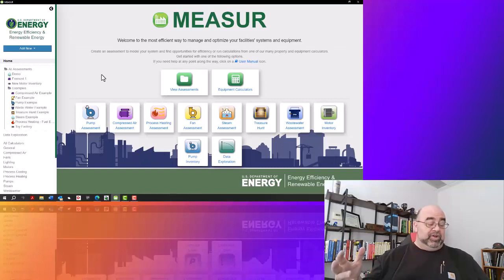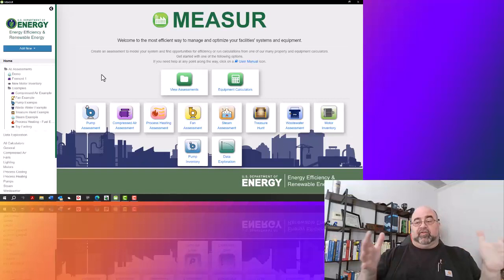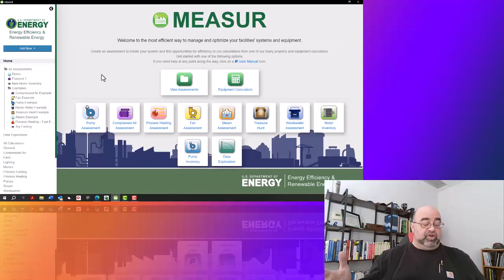So power measurement, you want to basically just record the usage, like several cycles or whatever the operational period is. You get several sets of that data and it gives you an idea of what the energy profile is for that equipment. Airflow measurements, when possible, and then pressure measurements, and those can actually be off of any pressure indicators in the system. And then, of course, leak detection. Now, leak detection is usually ultrasound. So you want to use leak detection systems. And both through the leak detection systems, but also by looking at pressure drop, you can make some improvements.